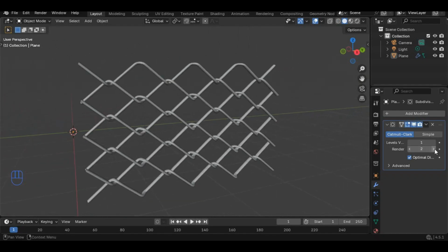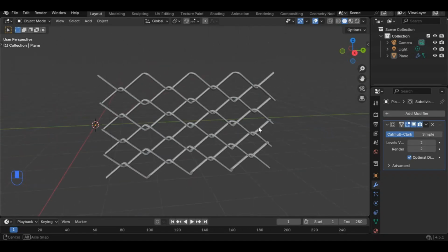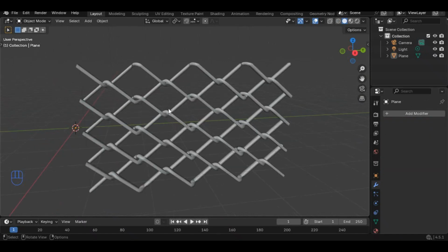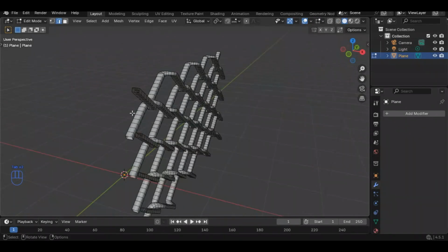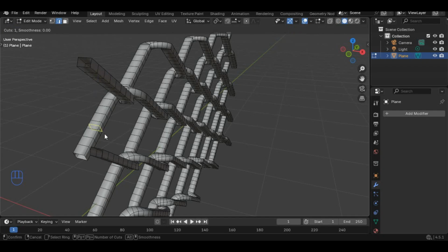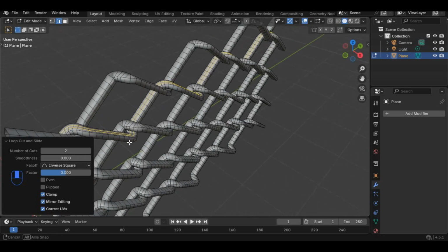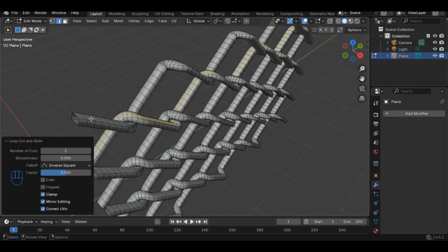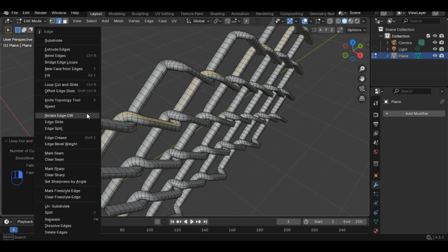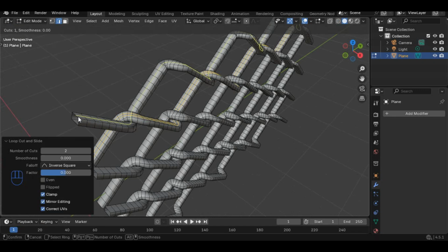And you can also make it even a little bit cooler if you add some loop cuts to this. You have some loop cuts, so you can give it, let's say, two loop cuts, and you add it all through. The geometries are actually linked. Once you get a loop cut here, it goes all the way through.